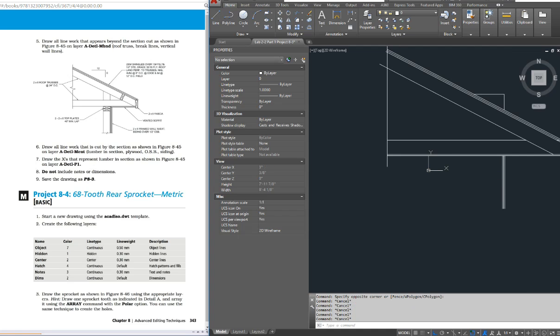So now, again, I've got a 2x6 top plate. So these walls are not 2x4 walls, they're 2x6s. So I think it's going to be easier if I just draw a rectangle right here and say at 5.5 by 1.5, and copy that from here to here.